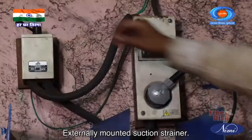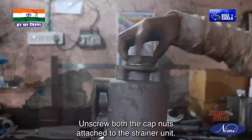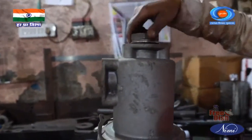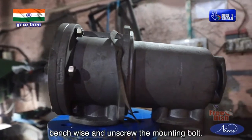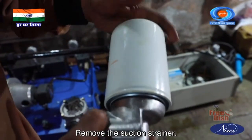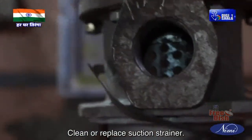Externally mounted suction strainer. Turn off the hydraulic system. Unscrew both the cap nuts attached to the strainer unit. Hold the strainer unit bench-wise and unscrew the mounting bolt. Remove the suction strainer. Clean or replace the suction strainer.